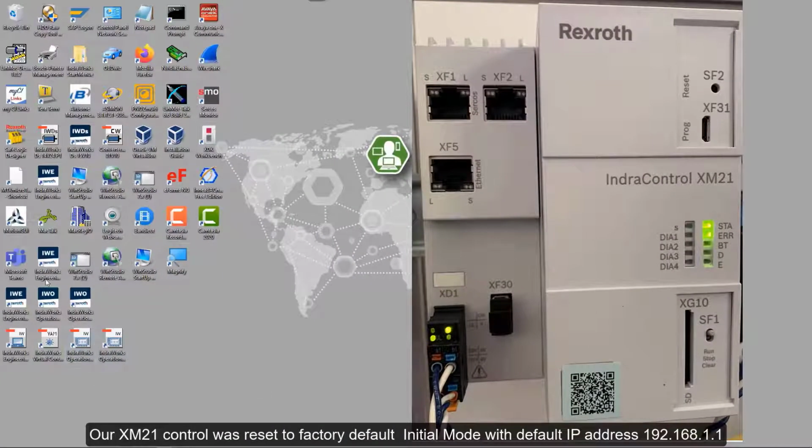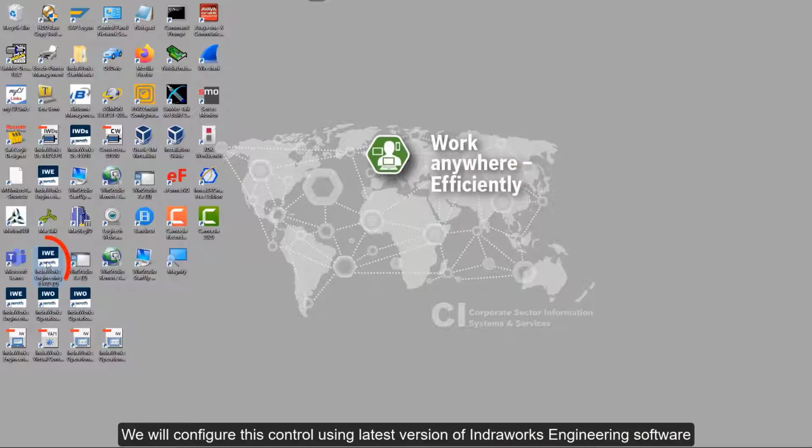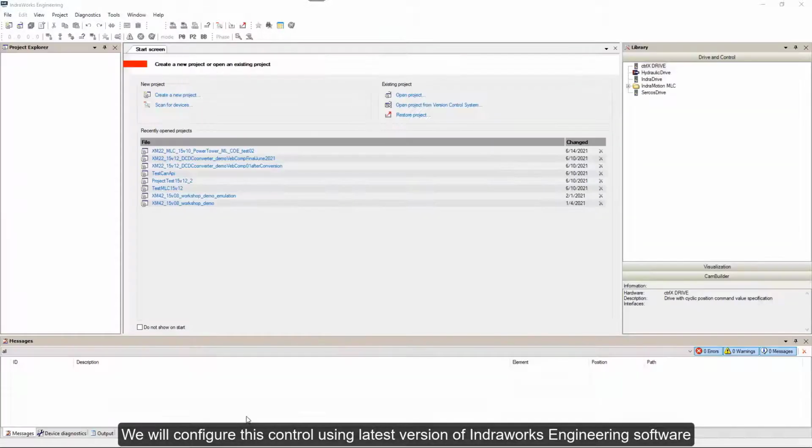Our XM2x control was reset to factory default initial mode with default IP address 192.168.1.1, and will connect to our engineering laptop using port XF5. We'll configure this control using the latest version of IndraWorks engineering software.